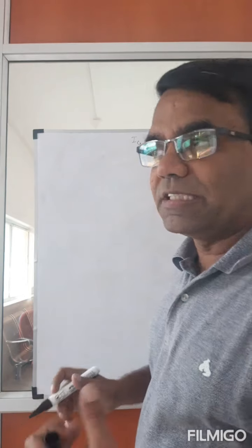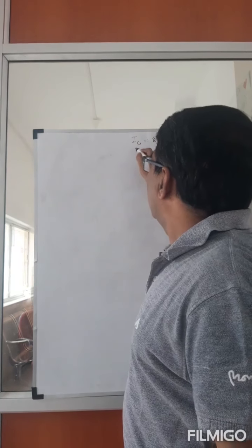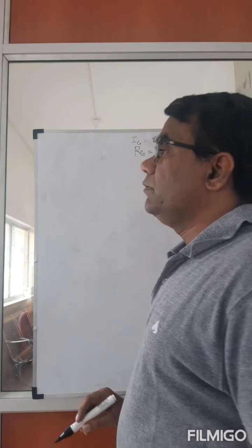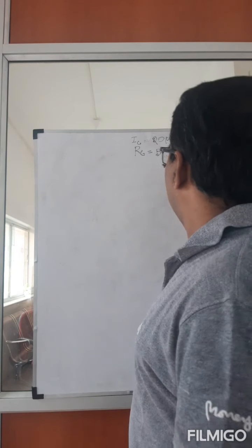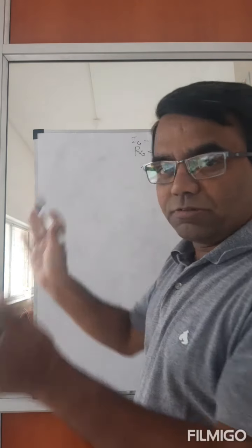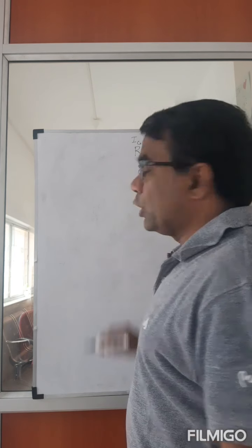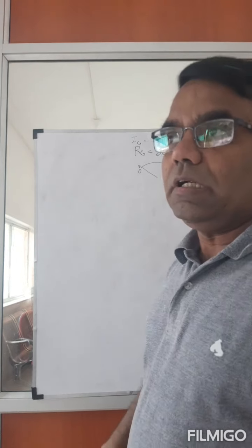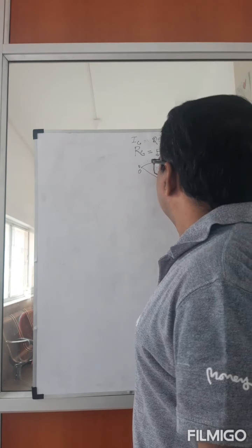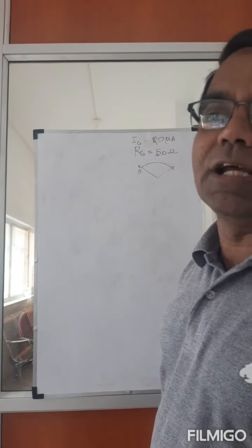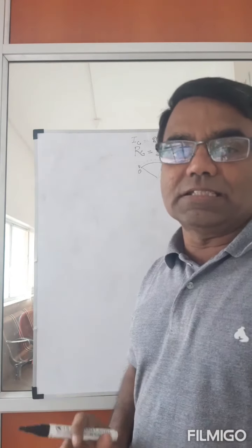Clearly, you have a coil there, it's a conductor, and it will also have resistance. So the resistance of the galvanometer could be taken to be, say, 50 ohms. I'll call this the resistance, RG, which is 50 ohms. And you have the scale on the galvanometer and a pointer that will point to 0 when no current flows through it. And it will have a full scale deflection for a current of 20 microamperes. This is how I've designed this galvanometer.